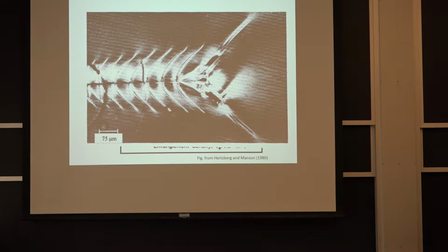Some of the things I wanted you to remember was the effect of molecular weight on the long-term properties. If you remember, there was a counteracting effect where if you have high molecular weight, sometimes it's harder to crystallize. So with less crystal in the polymer, you're softer when you do a tensile test, a short-term test, but you're just much stronger against cracking, was one of the takeaways. Another takeaway was you can save money with plastics, especially if you don't have to provide coatings for environmental protection. But there are some limitations.